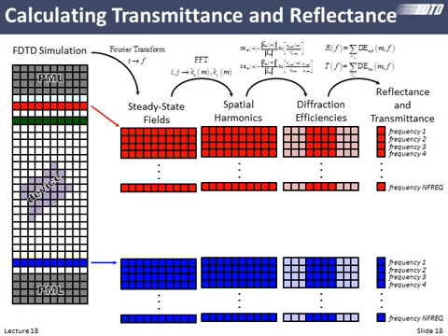So here's how I visualize the arrays and how we're storing things in memory. So on the left is our finite difference time domain grid. We have our device. We have a spacer region between it and the PML. We have a region where we're injecting our one-way source, so our source just travels downward. Above that one-way source, but before the PML, this is where we'll be recording our reflected fields. And all the way down the bottom is where we're recording our transmitted fields. We call this the transmission record plane and the reflection record plane.